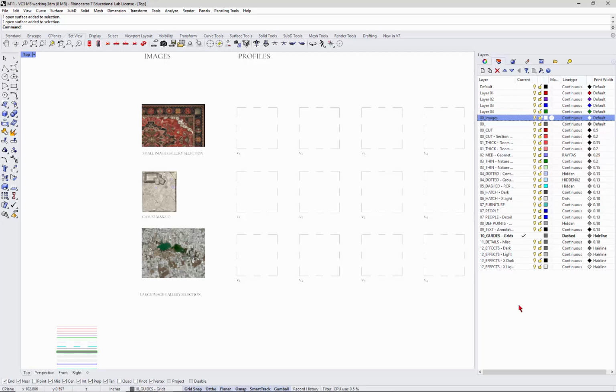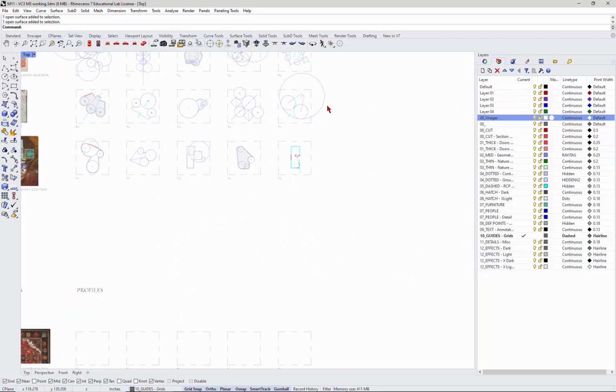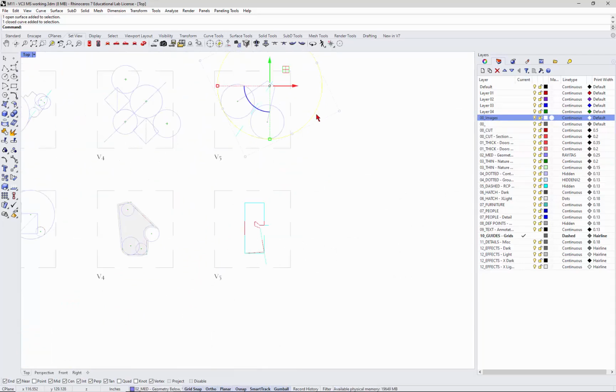Typically, what you're going to get in a drawing set are 3 basic line weights, and then you'll have some intermediary line weights for extra and additional emphasis for purposeful use. But the 3 basic line weights that are pretty well divided up. These layer names don't necessarily correspond with what these up here are used for. So for example, if I pick this, which is a dashed line, right?